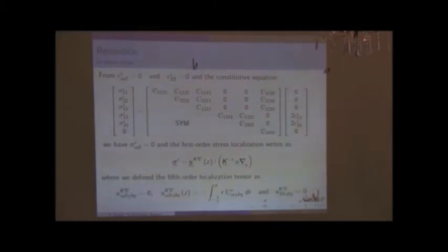This is from the auxiliary problem. The only unknown were the transverse shear strain, and the other strains are 0. We know that from the auxiliary problem, and this tells you that the in-plane stress is 0. So this sigma 1, the stress of order 1, is purely transverse shear, because of the uncouplings.